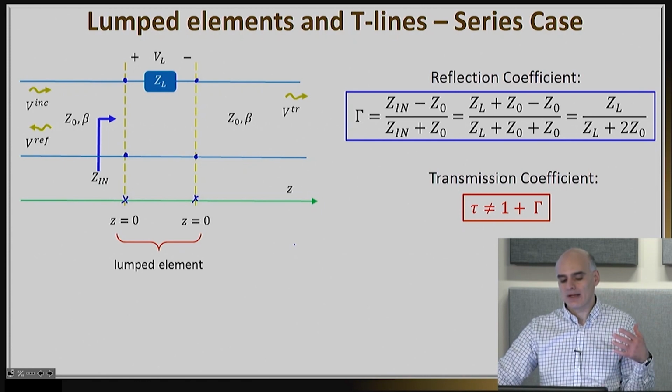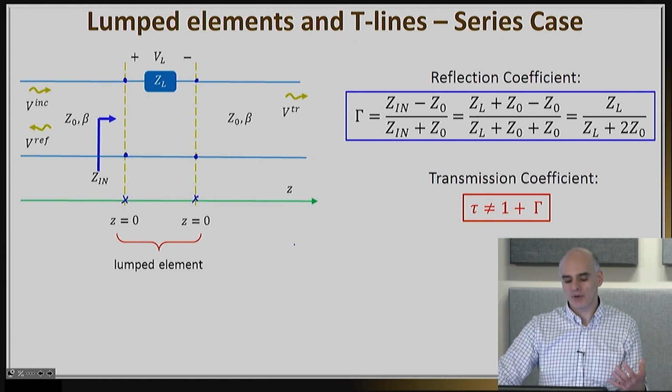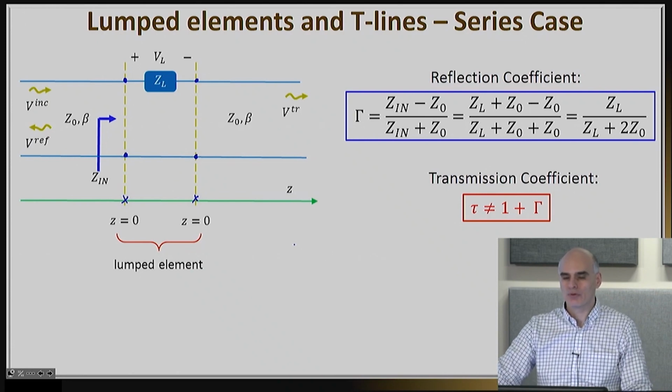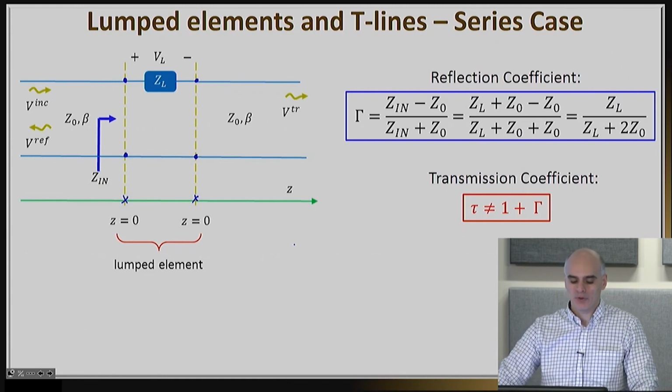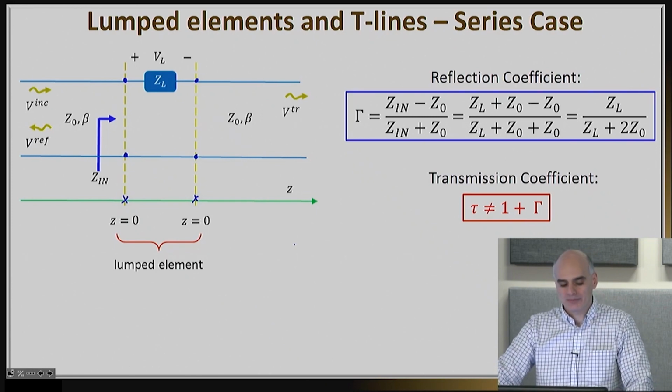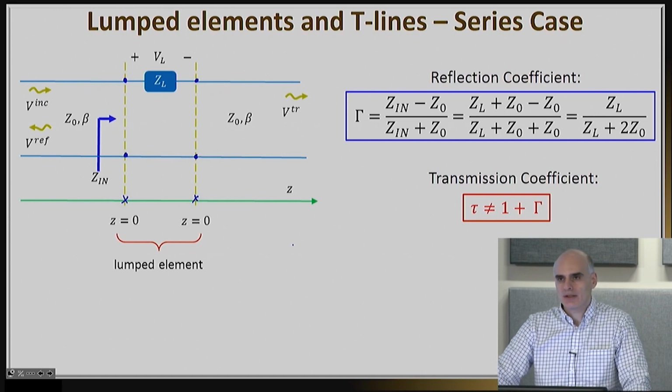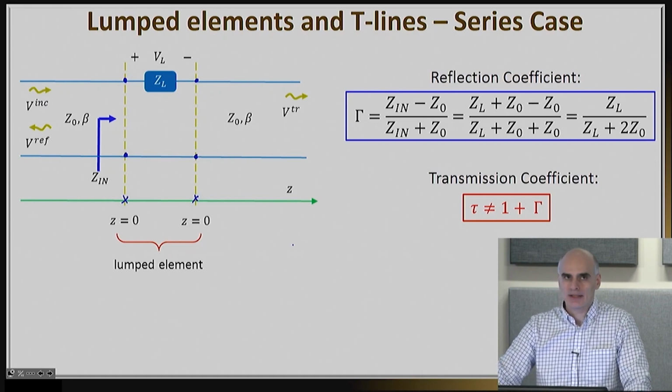And I know that when we're thinking about it from a geometry point of view, that doesn't actually seem reasonable. But when you look at it from an electrical point of view, a lumped load means it has a physically 0 size. And so that means that both of these nodes sit at z equals 0. Now, besides this complexity, everything else, the analysis technique, is actually identical.